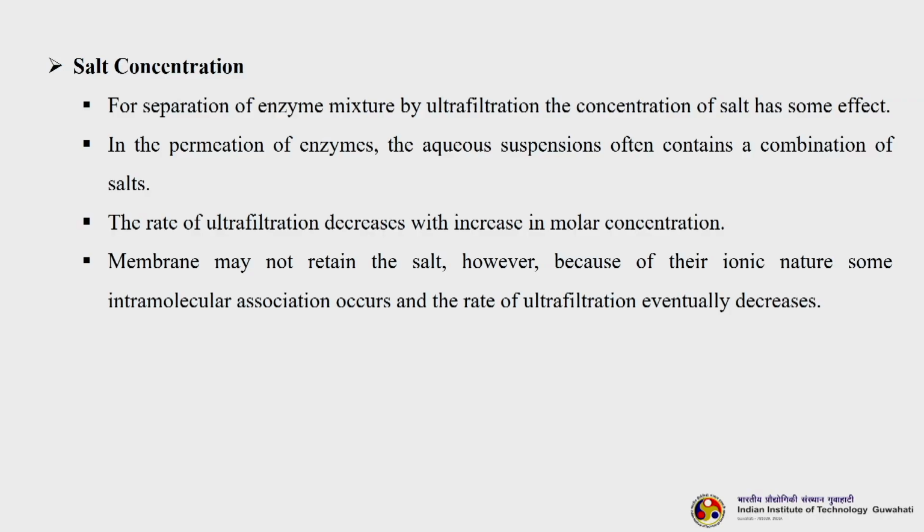Now, salt is not always used, but in certain applications salt is used in a buffer medium to enhance the performance. Especially for separation of protein and enzyme mixtures by ultrafiltration, the concentration of salt has some effect. In the permeation of enzymes, the aqueous suspensions often contain a combination of salts. So, there may be more than one salt also possible. The rate of ultrafiltration decreases with increase in molar concentration.